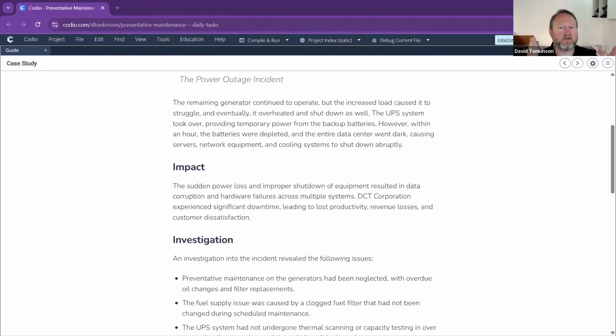Bearing in mind the diesel generators are supposed to kick in within 30 seconds, that gives them a little bit of leeway, doesn't it? And they had N+2, I believe, at their data center. So they had 2 spare diesel generators in case 2 of them didn't fire up. Now they know they can run those diesel generators and it will power enough to run that data center as long as they've got enough diesel going into those generators.